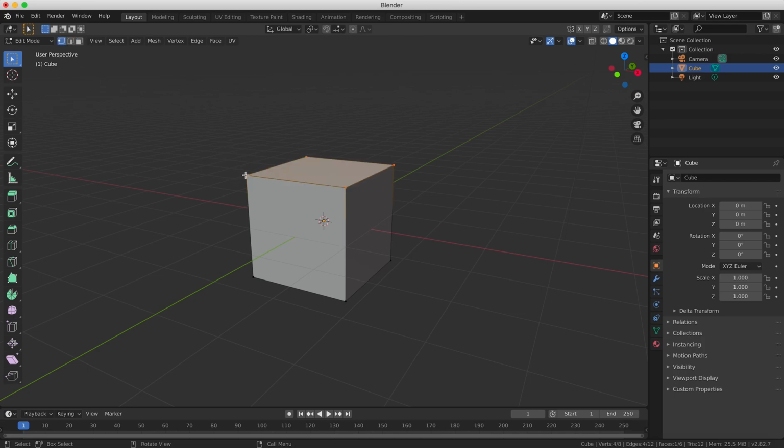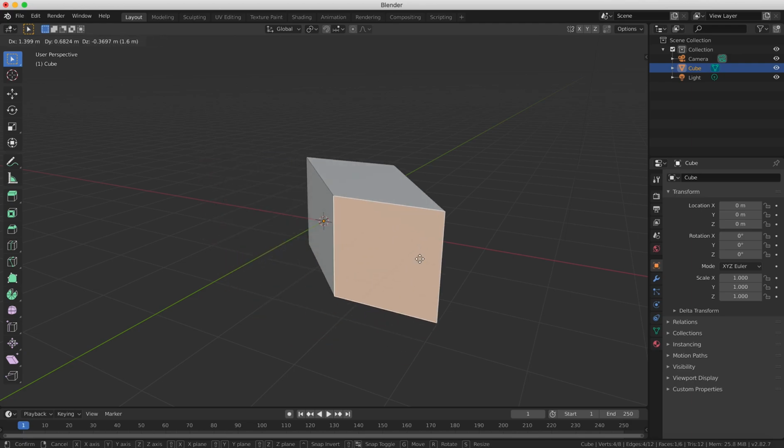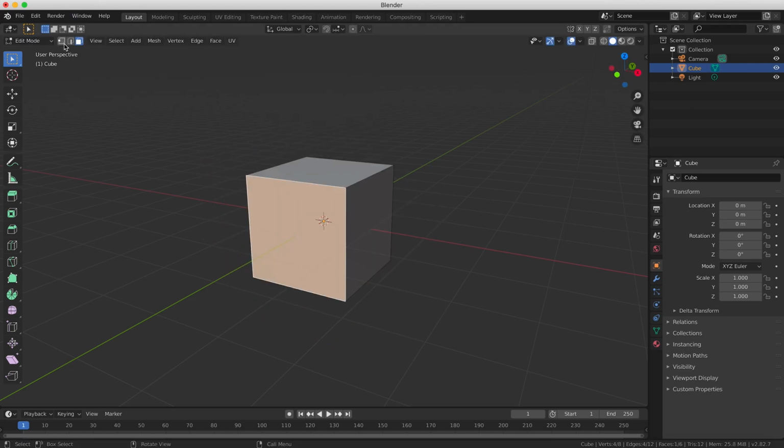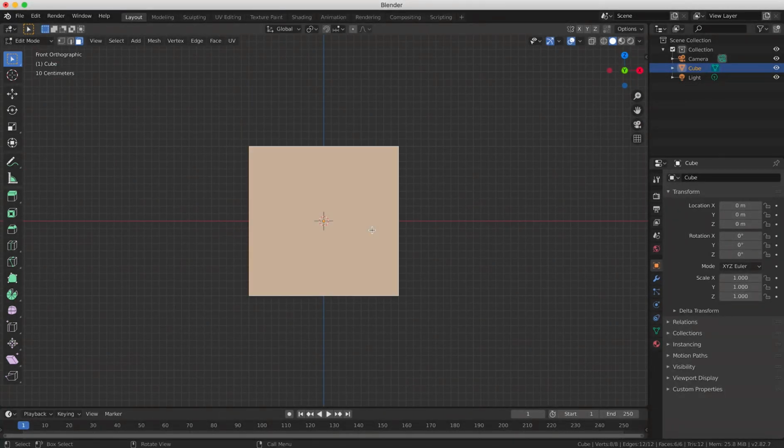As we saw before, you can scale, rotate, and move any of these in any direction, except the vertices, which you can only move. With box modeling, you begin with a six-sided cube. Choose Face Selection from the Properties panel and press A on your keyboard to select all of the faces. Pressing A again deselects everything, but for now we want everything selected.